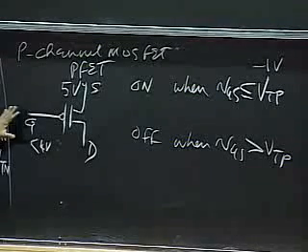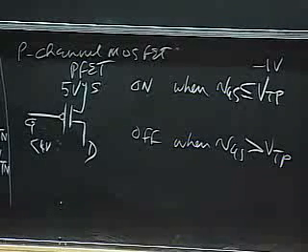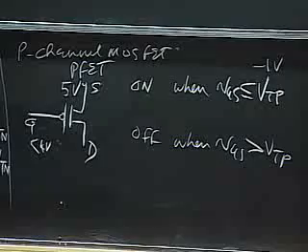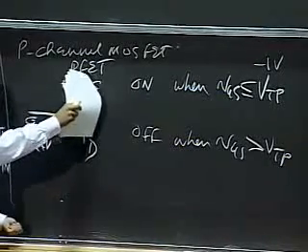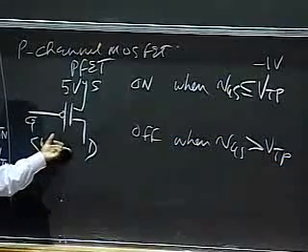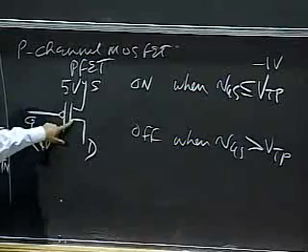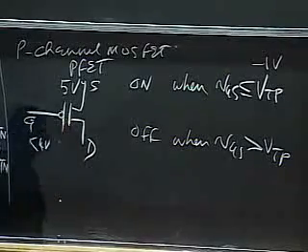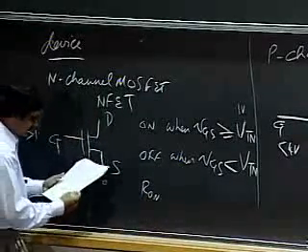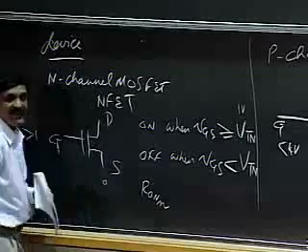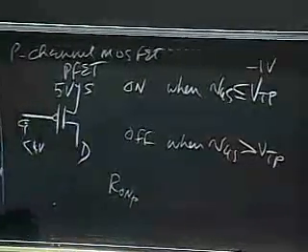Okay, so this is a complementary device that I postulate that behaves in a complementary manner. So when the gate voltage rises, this guy turns on. And in this particular situation, when the gate voltage drops below the source voltage, this guy turns on. Okay, so one is the rising guy that turns on. In this particular situation, when the gate falls, it turns on and shows some resistance. In this case, the resistance would be R on. And to show that it's N-channel, let me say N. And in this case, the resistance when turned on would be R on P to represent P-channel.